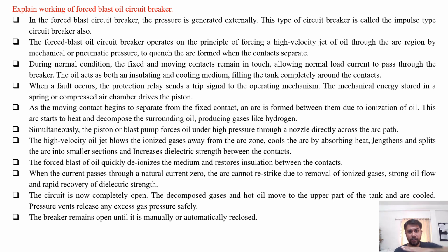In this, the operating mechanism connected with the moving contact and the pistons are interlocked. Whenever this moves in the outward direction, this moves in the downward direction. So these are the interlinking between the contacts and the piston arrangement. So this is the simple working of the forced blast oil circuit breaker.